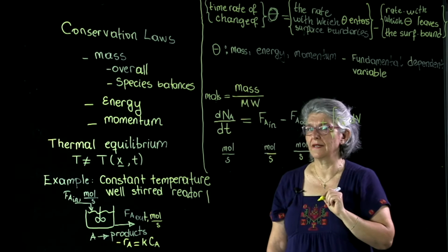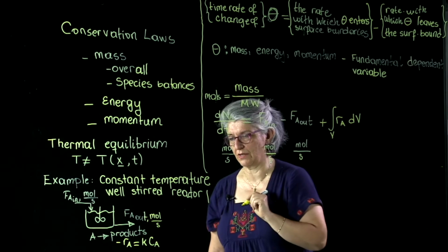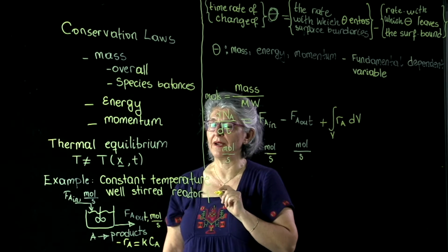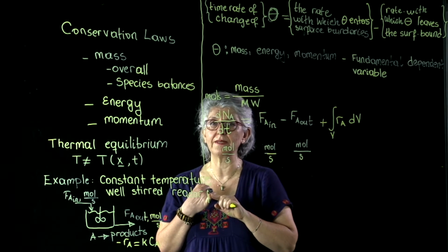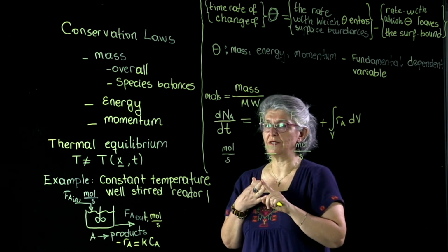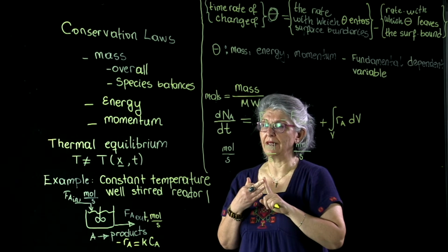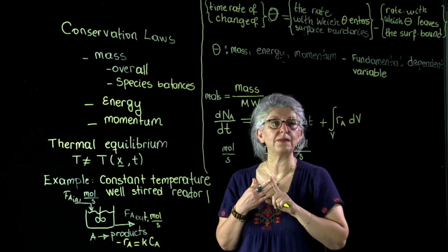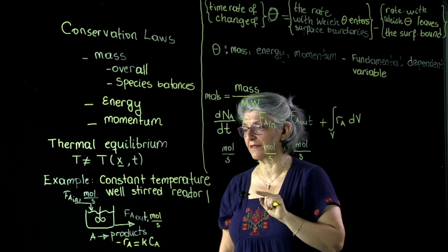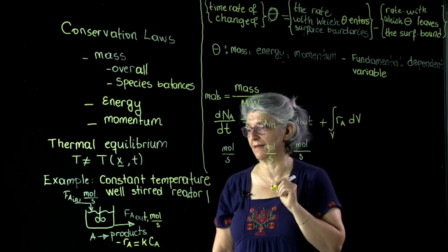The reason that I have put this equation in such an integral differential form is because I have been telling you about the temperature non-uniformities, the concentration non-uniformities, and even inhomogeneities in the flow domain. And as such, I anticipate a non-uniformity in the reaction rate, and by integrating throughout the reactor volume, I obtain an average reaction rate.